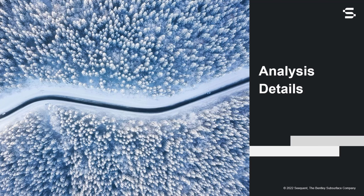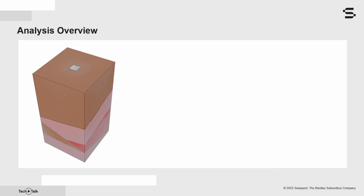Let us review the project in greater detail before starting our work in GeoStudio. At our project site, we will conduct a three-dimensional analysis to investigate the effect of a series of sloping thermosyphons installed below a 10 by 10 meter insulated slab-on-grade building. In this image, you can see the footprint of the building foundation relative to the overall domain.